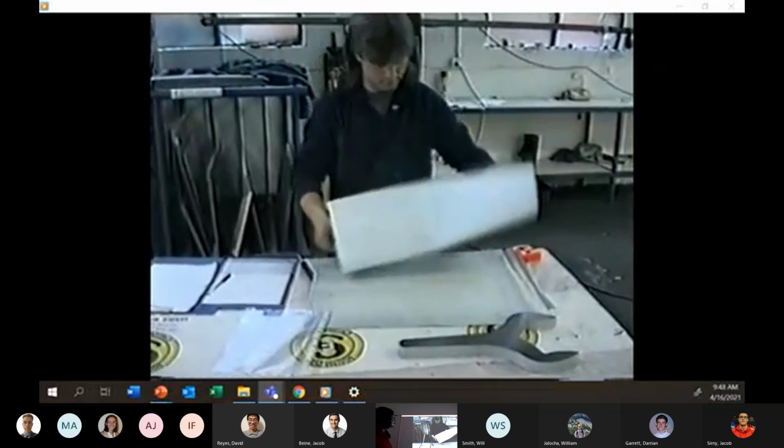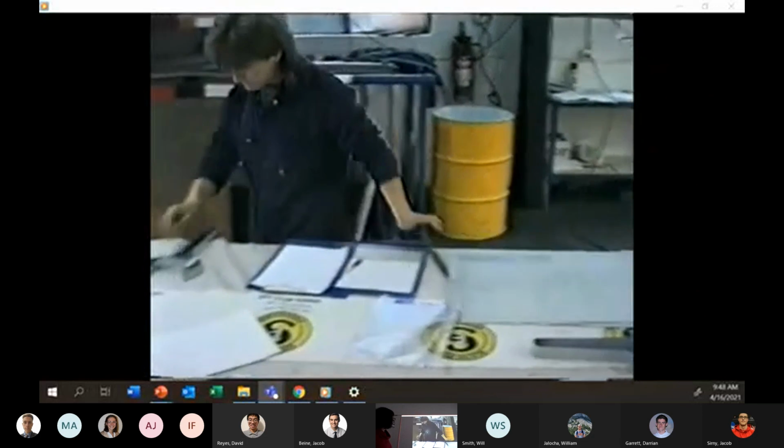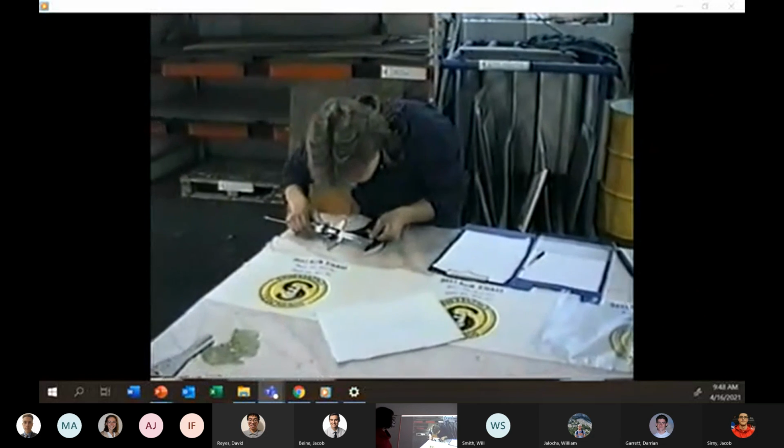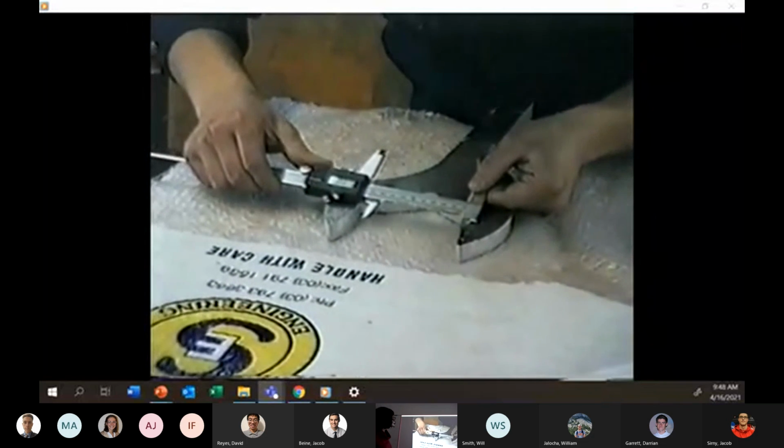The first and every following 20th spanner in each run is checked for dimensional accuracy. The tolerance on the spanner is plus or minus 0.2 of a millimeter, and the edges must be square.